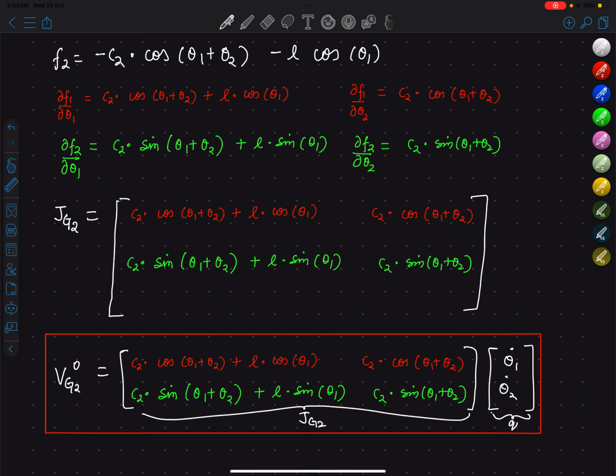But think about a manipulator which has 6 degrees of freedom, and also there the expressions become very large. You cannot differentiate each and every time. So if you know the Jacobian beforehand, you can calculate the velocity just by multiplying it.